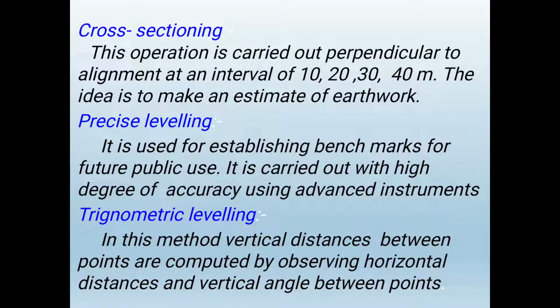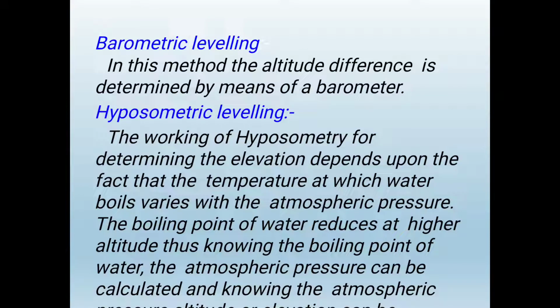Next one is precise leveling. It is used for establishing benchmarks for future public use. It's carried out with a high degree of accuracy using advanced instruments. Trigonometrical leveling. In this method, vertical distances between points are computed by observing horizontal distances and vertical angles between points.